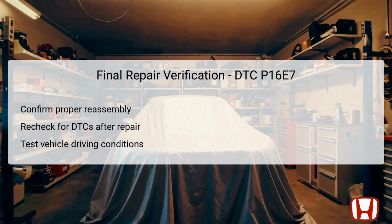Begin by visually inspecting all connections, securing any fasteners, and ensuring that the components are in their correct positions. Once you've confirmed physical reassembly, utilize the Honda Diagnostic System, HDS, to recheck for any present DTCs.